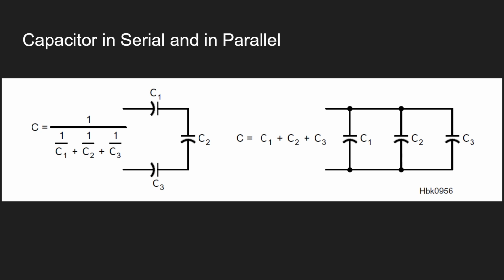I can parallel the water tank, right? So that I can choose each tank to store the water. But in series, when one capacitor is filled, it is already an open circuit. So the capacitance in it actually drops. So capacitor in series looks like the calculation of resistance in parallel. But in parallel, it is just the reverse of resistance. Okay, they are flipped. Very important. If you do your calculation, don't make it wrong. It's different.